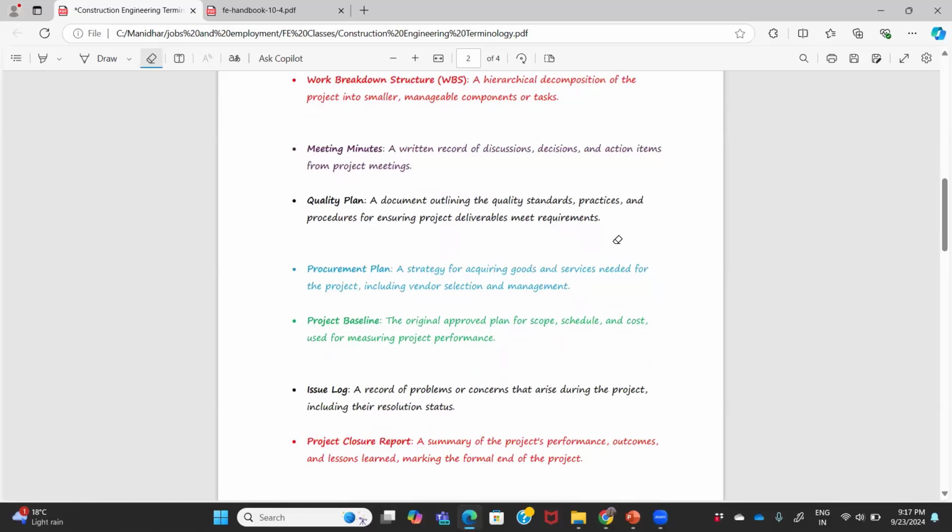And coming to the procurement plan, a contractor has to submit a procurement plan to the client saying that my materials come on so-and-so date. Unlike regular material like road base, aggregates, concrete, or steel, we need not give a procurement plan for these things, but we have to give one for certain single items, like whenever the paving material lot comes to the site, or material like your underground tanks, or any customized item. So a contractor must give a procurement plan for those goods to the site. That is what the procurement plan is.